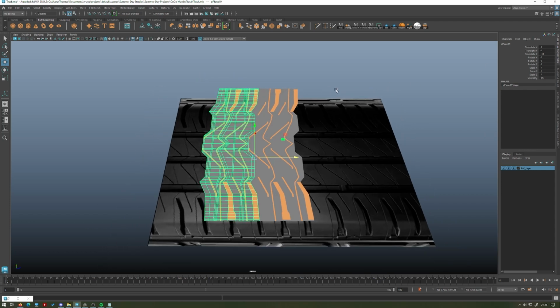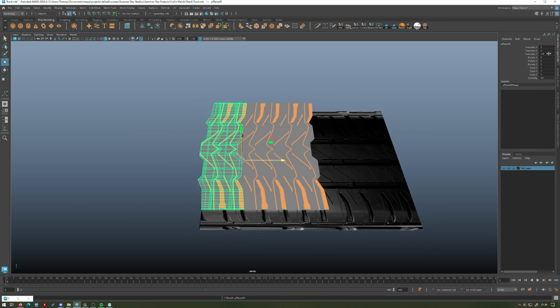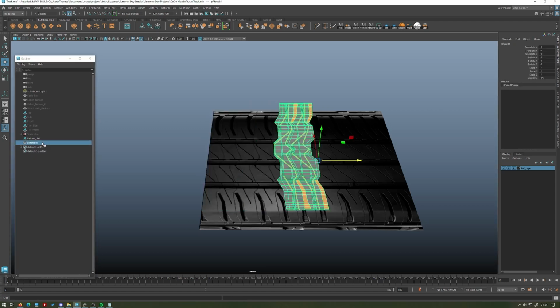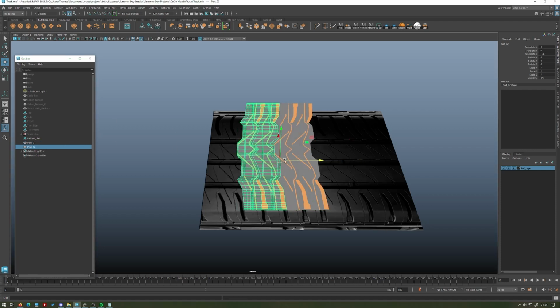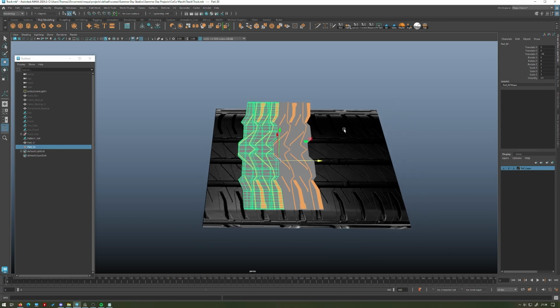In order to get this to do that over and over again without us having to do it ourselves, if you just then press Shift D, it's then going to duplicate the previous action and double it. So 14 times 2 goes to 28. And we know that we need exactly 44 of these. So perhaps what you could do is, if it has something like this, maybe call it part 01. And if I duplicate this now, it's going to go out to 02. So I'm going to go ahead and quickly duplicate these out.